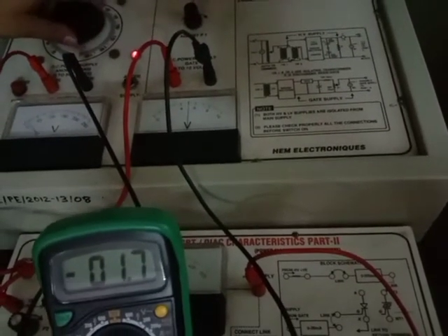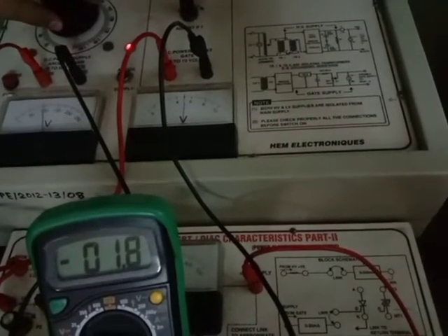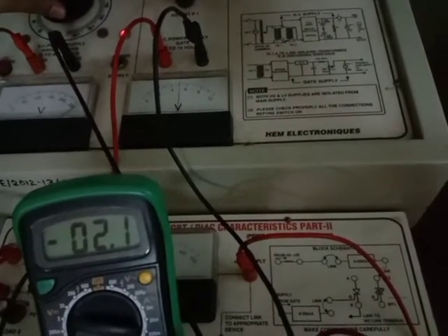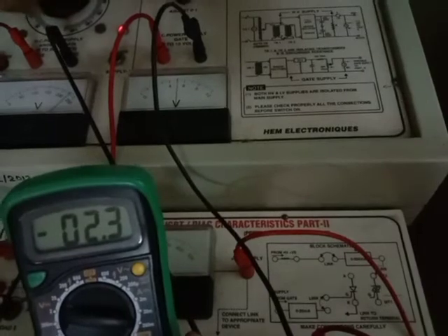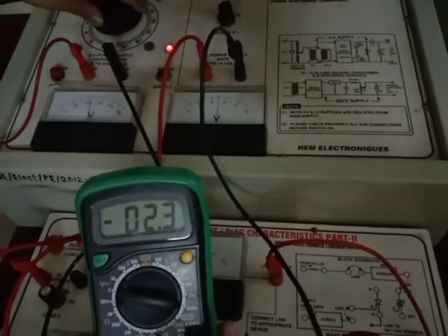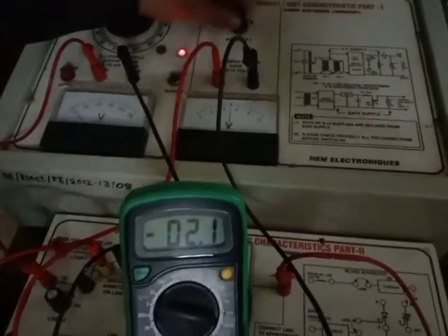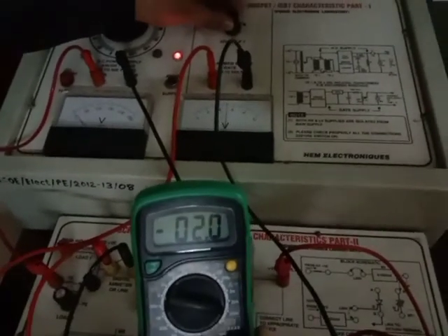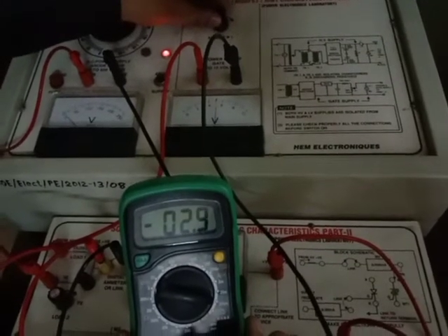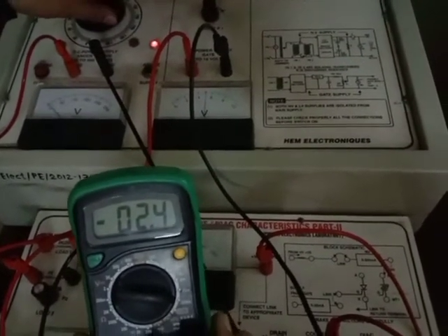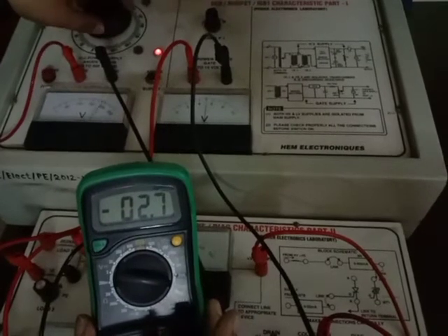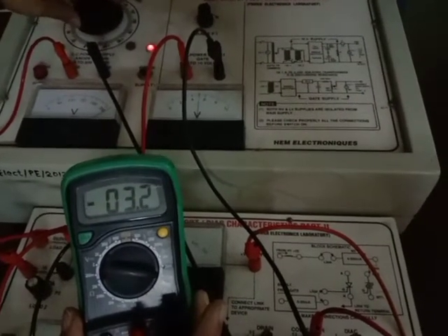Okay, now let us see. As I increase VC, you'll see that the current is going to increase. So 1.92, and after that it is going to remain constant. That indicates that the device has become saturated. So even with the increase in the VC, it is not going to change. In the same way we are going to increase this VG to a little bit higher value, say 2.5. At 2.5 if I increase this, you'll see that the current is going to increase but then remain constant. So at 3 it is going to remain constant.